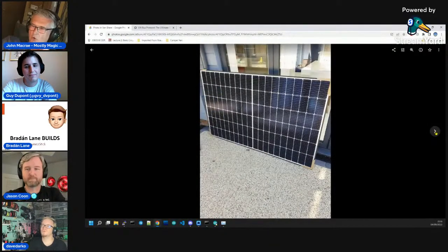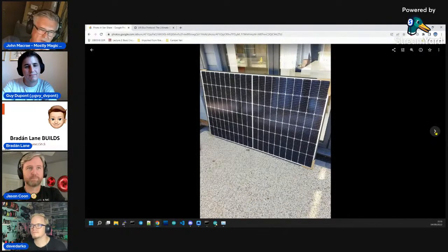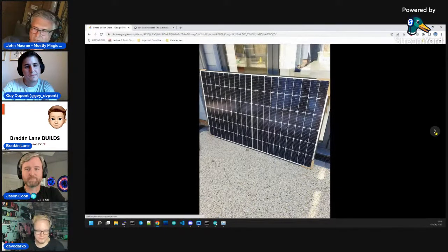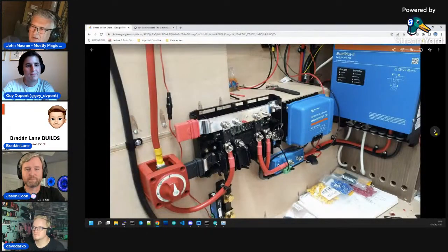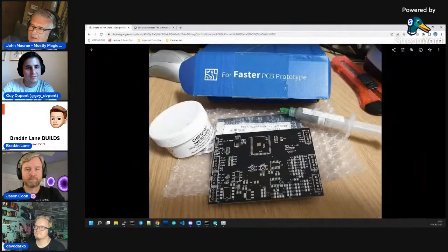I added solar. That's a 380 watt solar panel for the roof, and then started wiring it all in. So DC to DC converters to provide control, battery cutoffs, and obviously a massive main switch. And of course, a battery pack like that demands its own battery protection system.